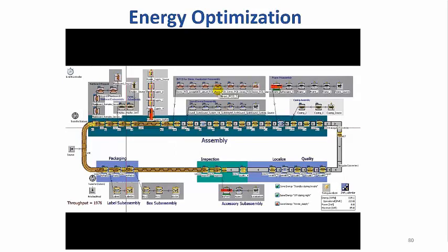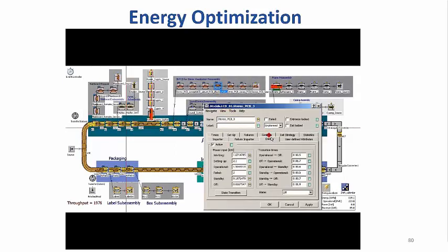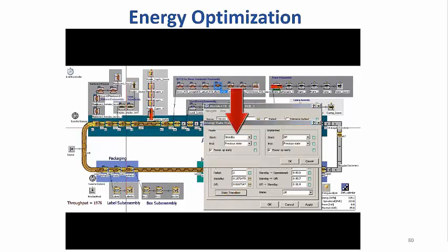The secret behind modeling these energy-saving measures is the State Transitions button on the Energy tab for our station and conveyor objects. The left side tells PlantSim what to do at the start and end of a pause or break within a shift. Here, standby is specified. The right side tells PlantSim what to do at the start and end of unplanned or off-shift time between shifts. Here, off state is specified. And last but not least, the Power Up Early option lets you power up equipment early so that your equipment is ready and raring to go as soon as working time pops up, so you get no decrease in throughput.